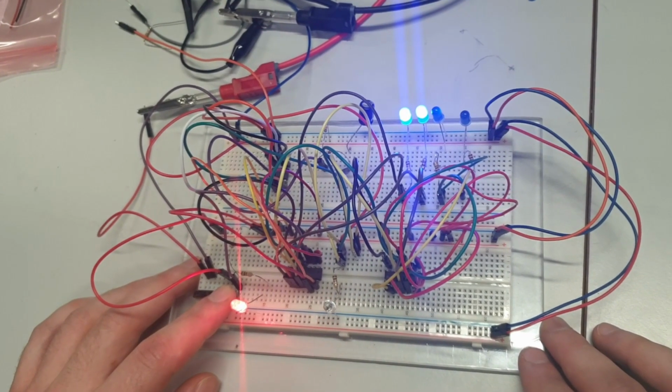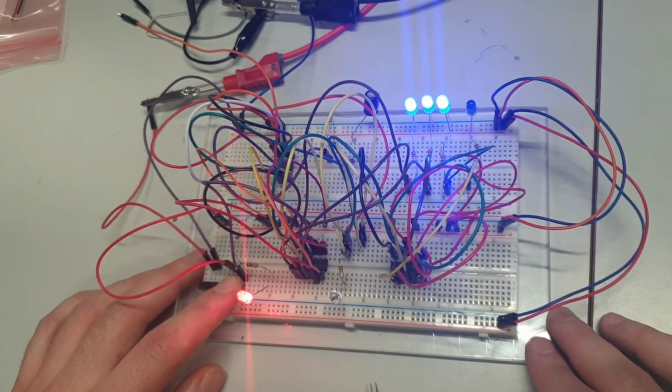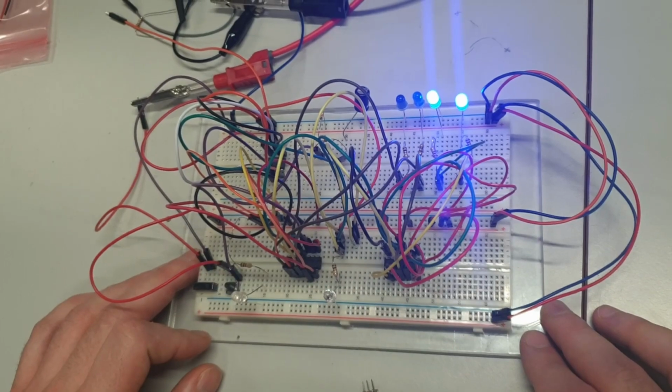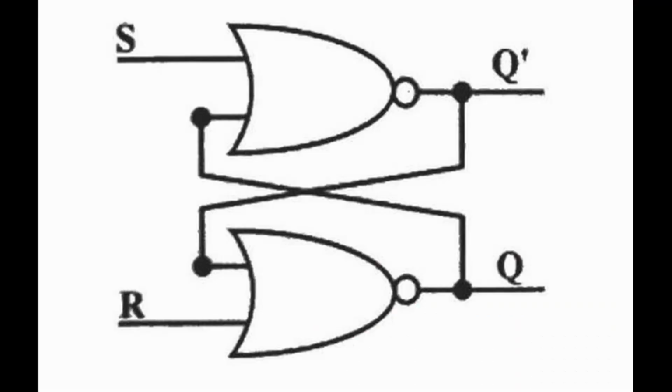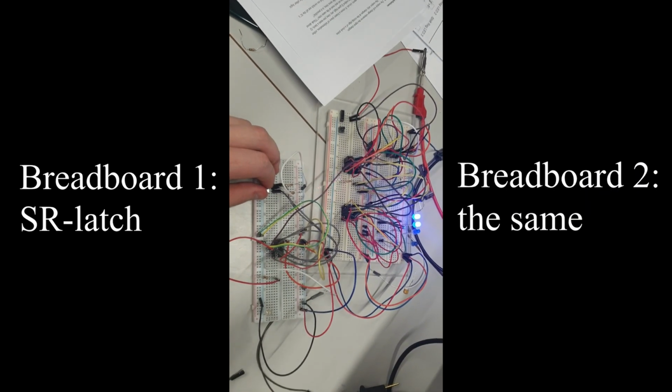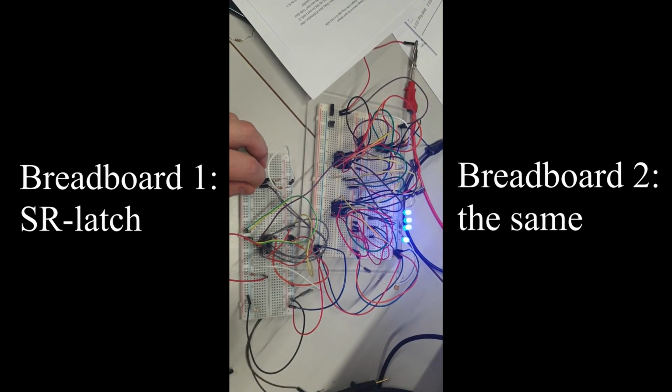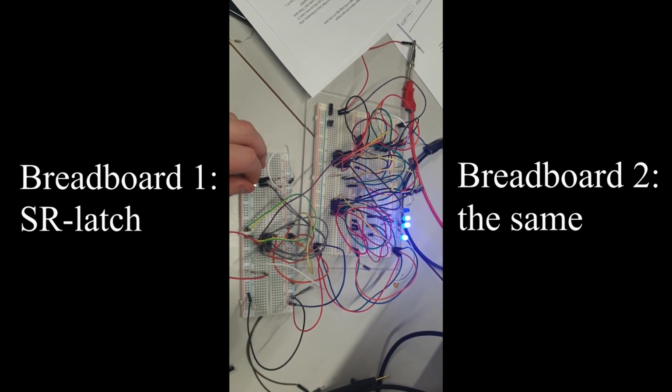However, these lights seem to turn off 2 at a time when using the 100 microfarad capacitor, possibly because of background noise coming from the push button. We decided to use an SR latch between the push button and the first D flip-flop to minimize the noise. With this addition to the circuit, we could get the right kind of results for the 100 microfarad capacitor as well.